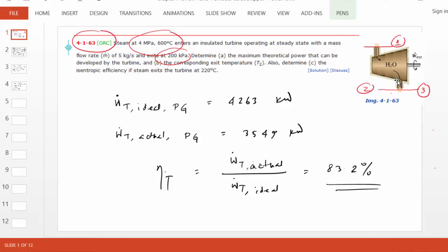When a phase change fluid is in the superheated form, it is more akin to a perfect gas. Essentially, what is a gas? A gas is a superheated vapor which is way, way superheated, far removed from the dome region. So if the steam is very highly superheated, the PG model will do a better job.